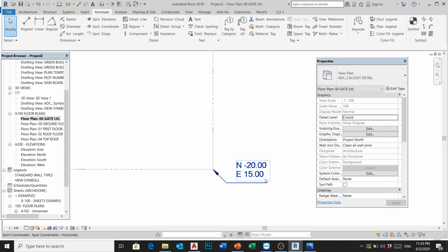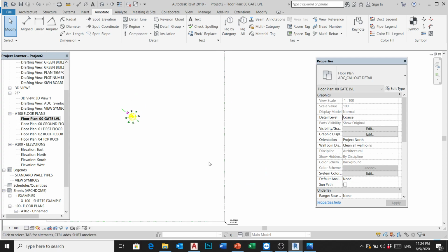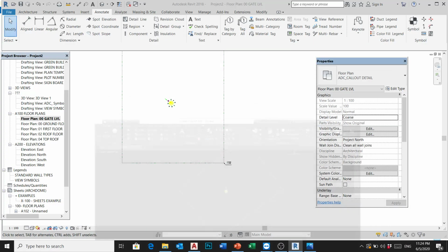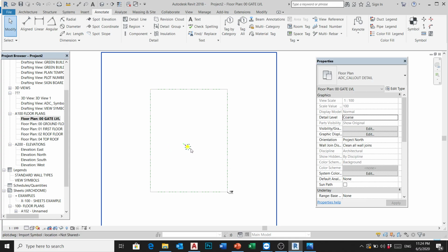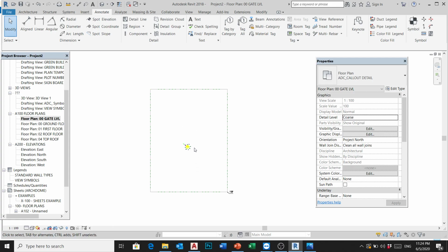Okay, this value is totally different than whatever we have. How will we use this one as per the CAD file, as we agreed, we already drew this one as per the coordinates. So what to do? We will just go to the first step. Now this is the project north, we have to bring it back to the true north for the purpose of the setting layout, which sometimes we have to present in the drawing as per the true north.